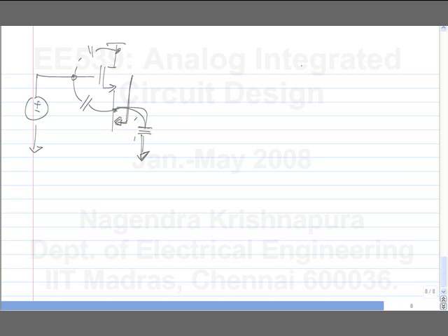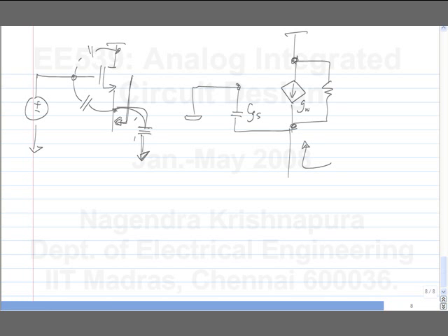So the incremental circuit looks like this. And I have the CGS of the MOS transistor. I have excluded the load from this. So what is the input impedance now? What is the output impedance now? It's the output conductance we had before plus the admittance of the capacitor.